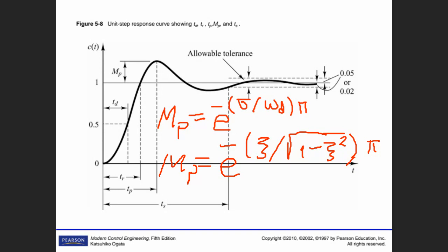The last thing we are going to find is to obtain the settling time. You remember that settling time in definition is the one where your step response begins staying inside the 2% band or 5% band. So your waveform is not now leaving that one.